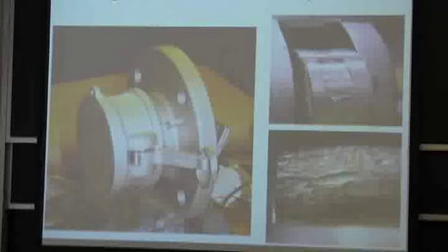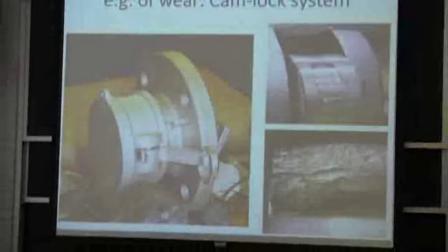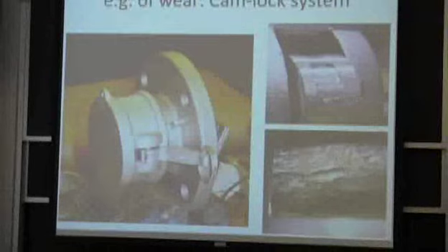We started looking at this and ran a few tests, like you see here, and started getting all these super-sized chips. So on the right image on top right here, you see these wear chips. This is bad. This is really bad. It's galling, that we call. So it's the removal of essentially pieces of metal, because in that case it was stainless steel and stainless steel. So two very similar materials, which means a lot of friction between them. Similar hardness means a lot of friction and adhesion.